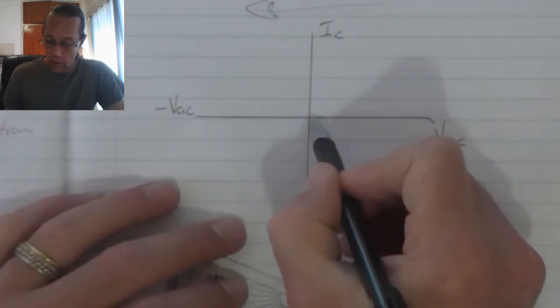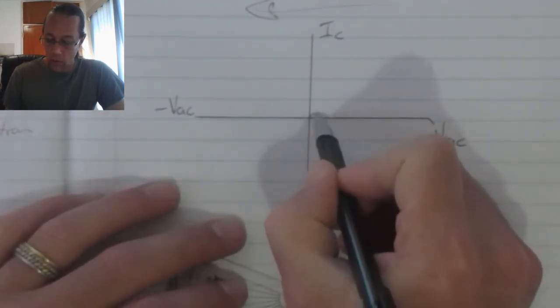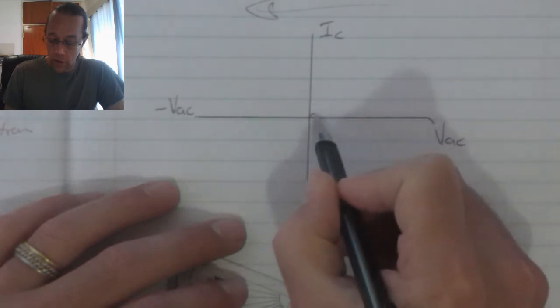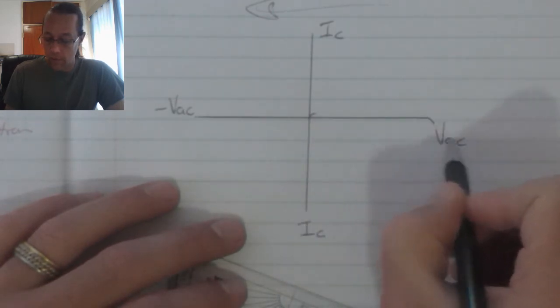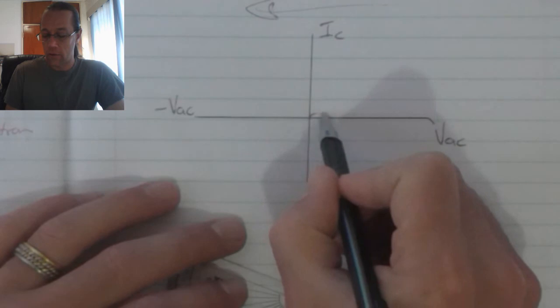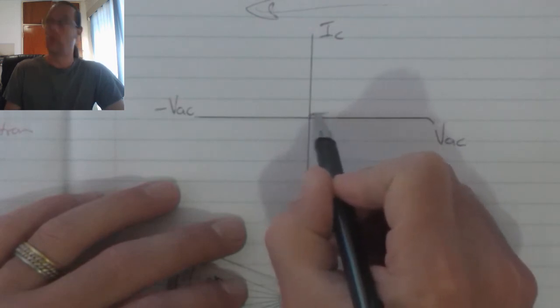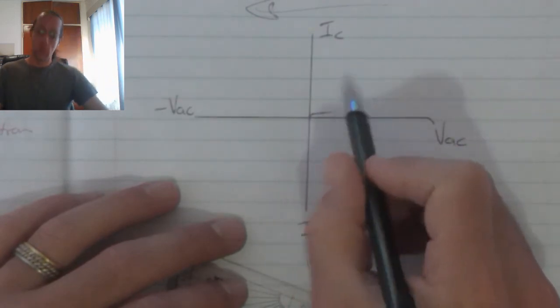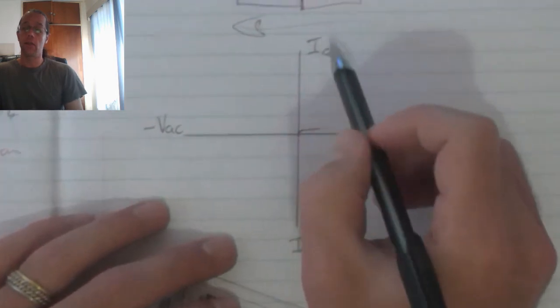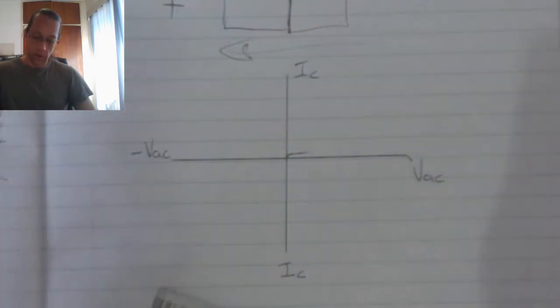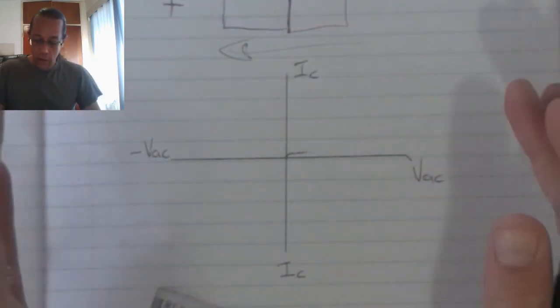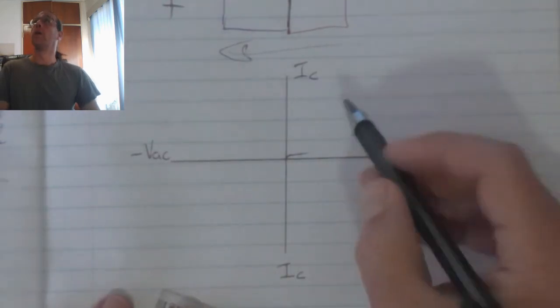And when we've got a small voltage, as that voltage increases, we will find that there's a small leakage current flowing through the component, and that is because of the changing size of the depletion region.